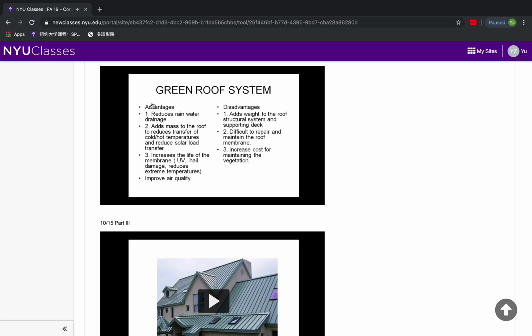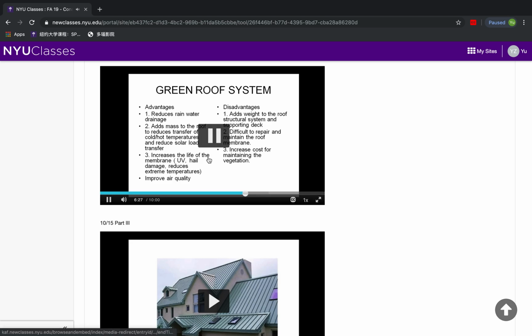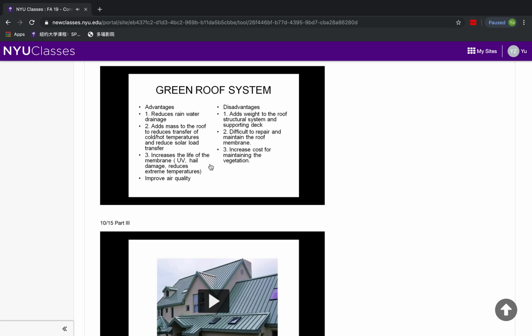The disadvantages are obviously you have plants and trees and things that need upkeep on that roof in the future. You need more structural capacity in your roof likely because you're holding the weight of the layers of soil plus the materials plus the added drainage. And it's difficult to identify if you actually have a leak that gets down through the lower levels. Where is it coming from on the outside? Some of them have to be treated or identified from the inside out, which is a much more difficult and costly repair.